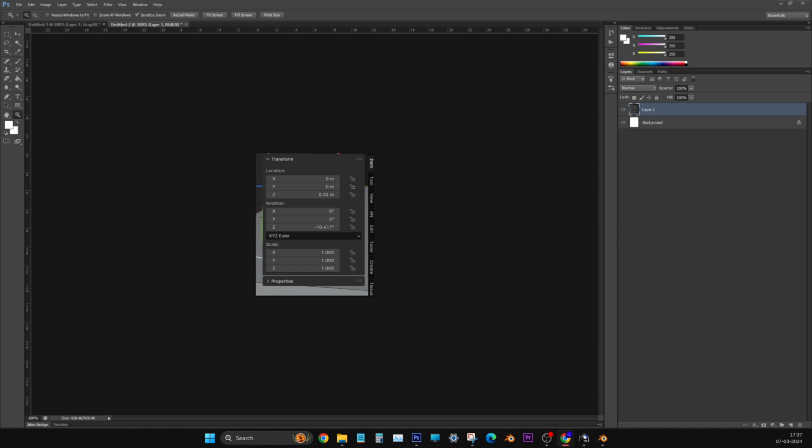So now press A on the keyboard. Now we have selected it. We are going to do unwrap, but just see the shape first. Zoom out and see how the shape looks. Switch off the X-ray. We don't need it. Now you see it is very flat, right? This is how it should be actually. Below this, thickness should be formed.